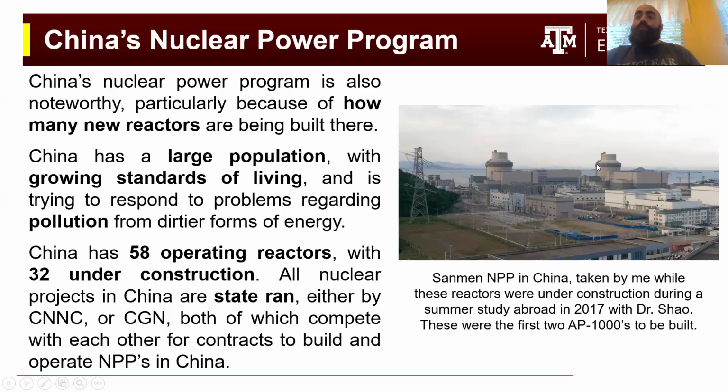Part of the reason they do that, it's a passive safety feature, is that if the plant were to lose offsite power, if somebody were to cut these power lines and they lost electricity to power their facility, then that might stop their pumps from running. And if you don't have pumps, then you no longer have forced circulation to flow through your reactor to keep your fuel cool.